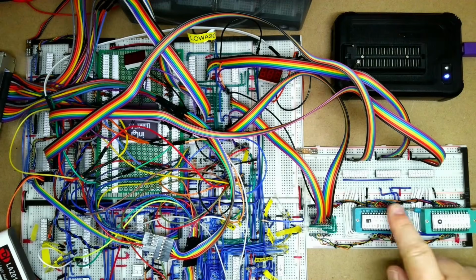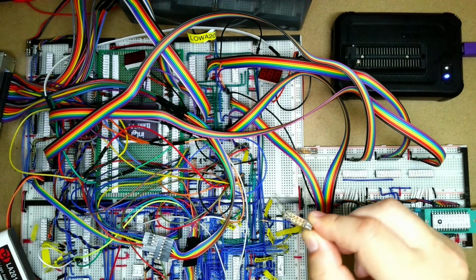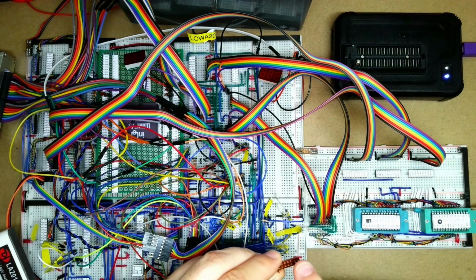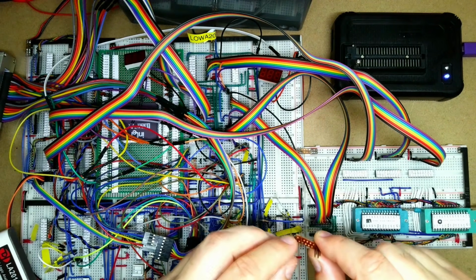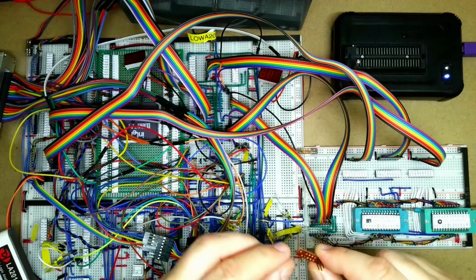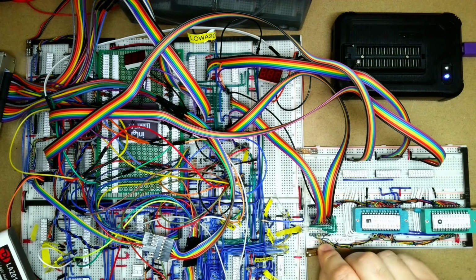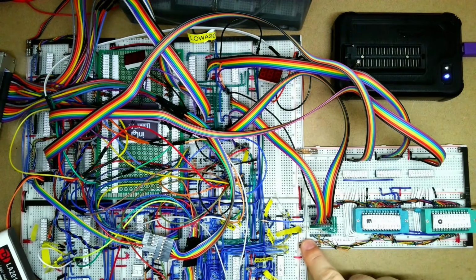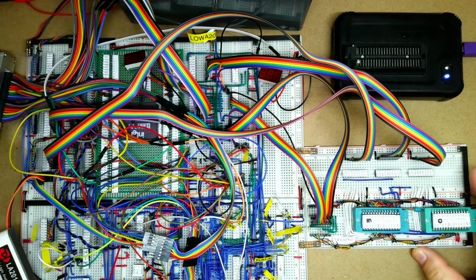I should also just say that I've connected this board up onto the rest of the breadboard here, and I made these little strip board VariBoard connectors. So the end that goes in over here has just got 2 pins on each of the power rails, and then there's sort of staggered ones here, so alternating rails here and a sort of diagonal. And this just means that we can connect the breadboards together at right angles, and the power will also be connected as well. So you've got one there and one there, so that should keep the board fairly stable. We probably need to shuffle things around when we add all of the bus rails and bus connectors and things, but for the moment this should actually get us going.